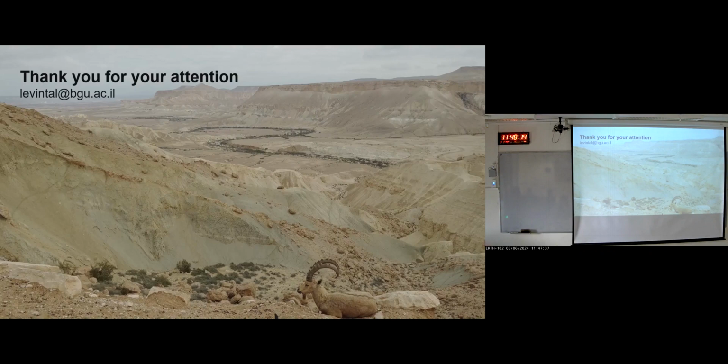And now we have a system running for a year. During that year, there was no situation in which all three sensors drifted at the same time. So one is drifting, but for the other two, we are doing averages and different algorithms. The one which is drifting is always being corrected back to the baseline values. But we have places in which we didn't succeed, and we abandoned that approach of using local sensors. It really depends on which parameter.